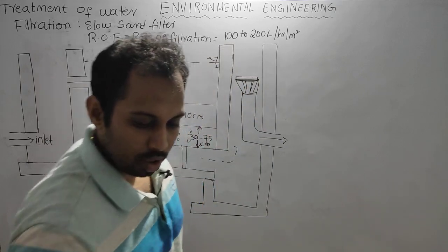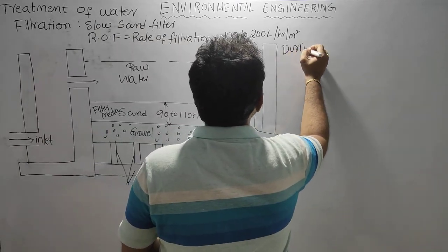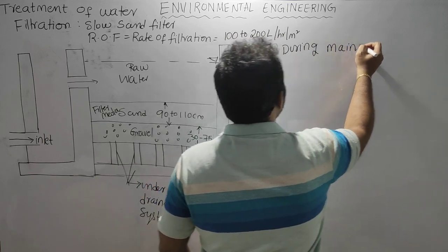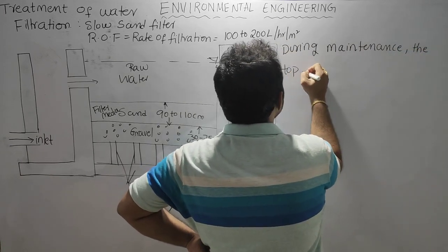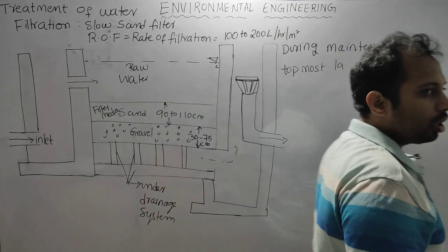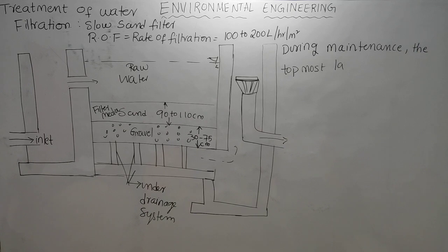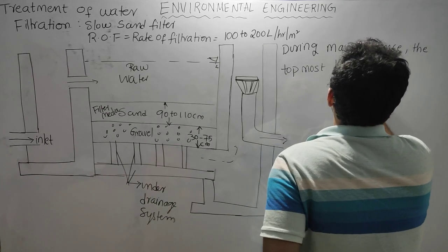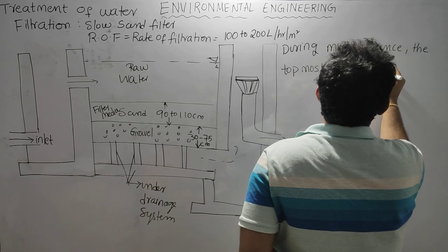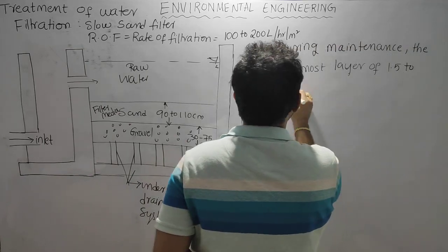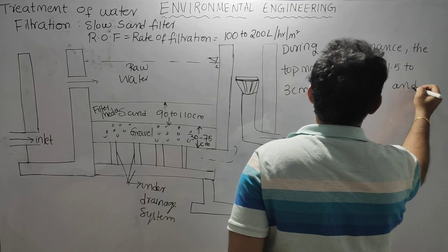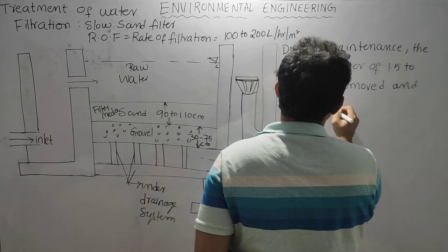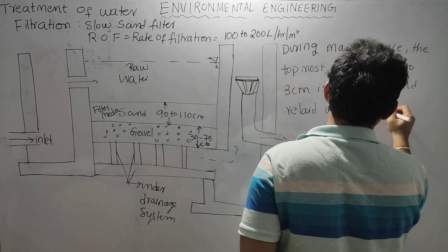So during maintenance, the topmost layer of about 1.5 to 3 centimeter is removed and relaid with fresh media.